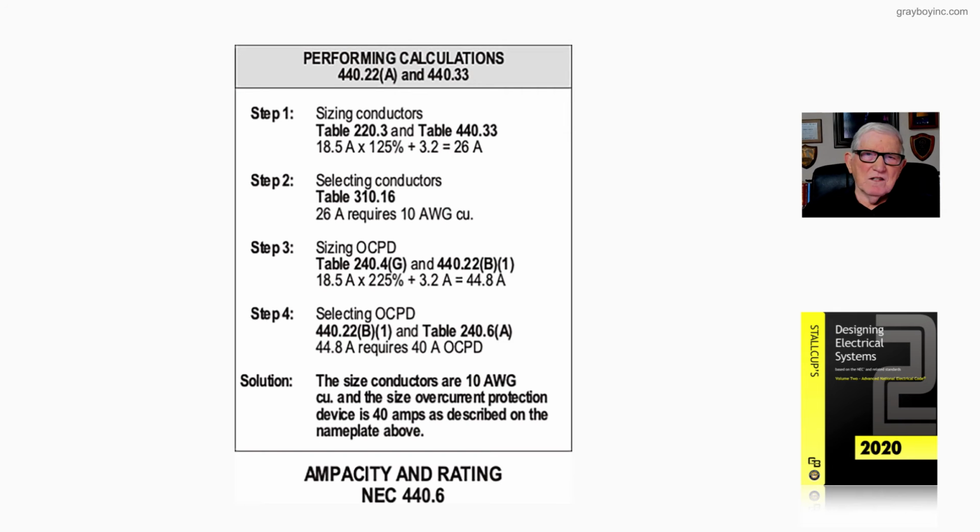Now, just as an example, if your AC unit was on a roof, say, usually the 225% is always applied. And depending upon usually the part of the country you're in, you may have the maximum of 225% applied because of the heat during the summer and high head pressures that build up. You don't want nuisance tripping. Or otherwise, 175% could be used to start your evaluation. So this is usually always a